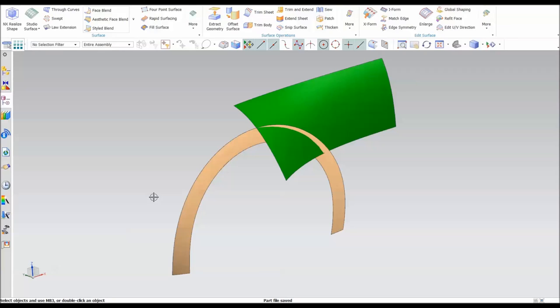Hello everyone. Today I want to talk about creating the transition from a fender up to the wheel arch. Now here you can see I have a nice surface and I need to create that transitory surface from here up to here. Now there are several ways that you can create this, and since this is an exterior body panel that's more than likely going to be sheet metal, it could potentially be aluminum, it still needs to be perfectly smooth, and still needs to have G3 continuity.